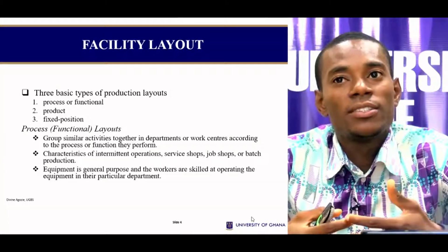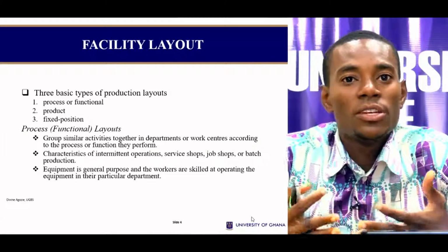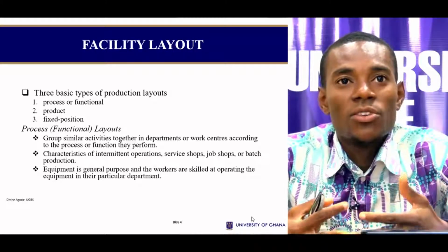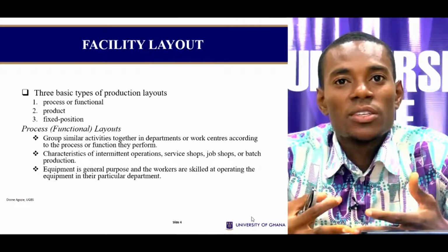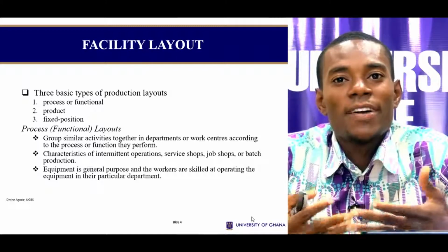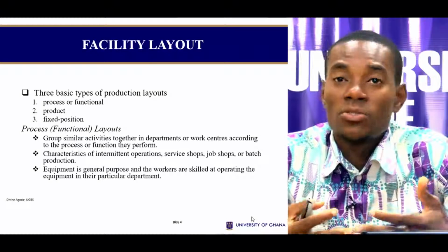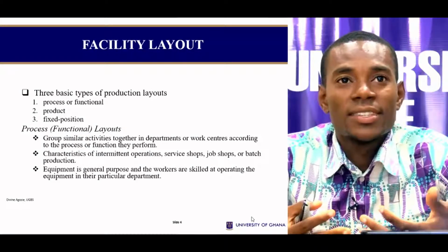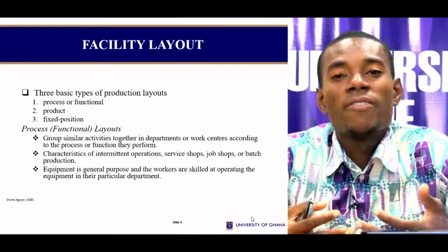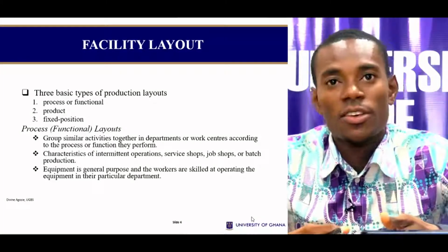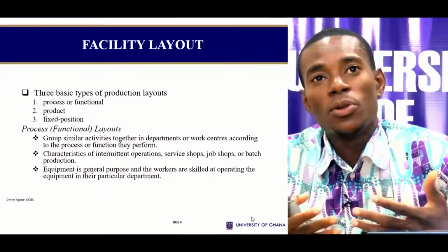Now, functional layout is basically saying that you arrange your factory floor, or you put equipment, in a manner based on whatever functions are done. So you group similar activities together in a department or work centers according to the process or functions they perform. If you come to the university environment, if you go to a block, and the whole block,